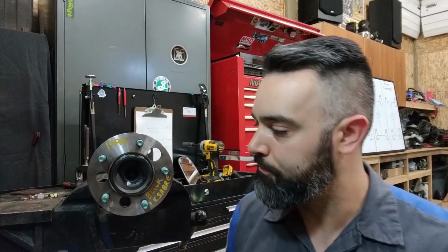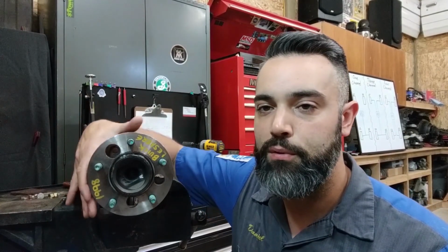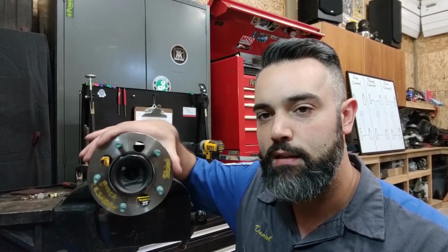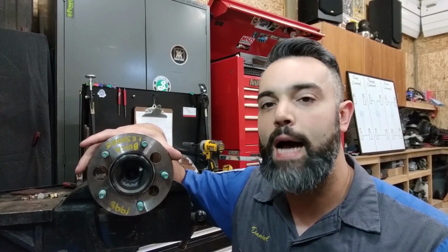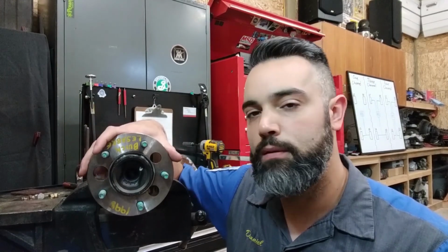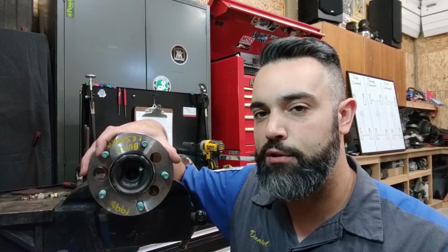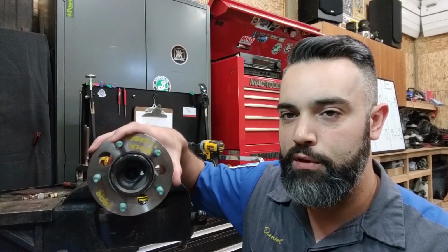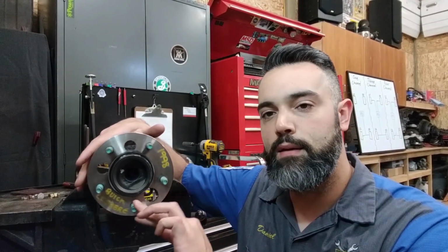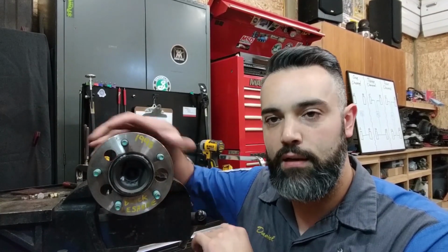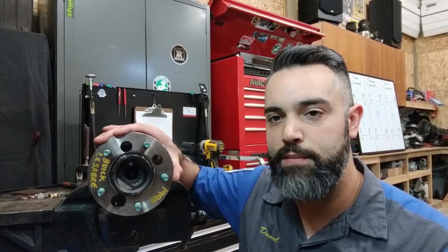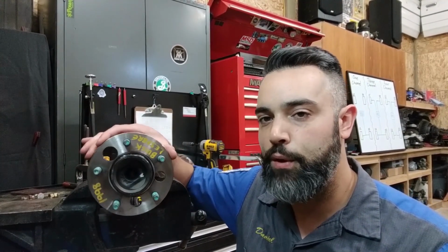The ABS control module, once it detects this wheel is no longer spinning, it stops. Then the computer isolates this wheel, and then it reduces pressure to that wheel. Once it reduces pressure, that wheel is allowed to spin again, and then the computer can command it to reapply the brakes, and it will pulse many times a second and allow the vehicle to slow down and maintain directional stability to avoid obstacles or other hazards in the path of the vehicle.